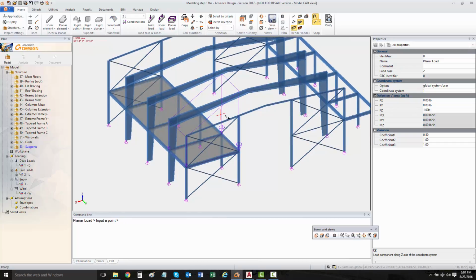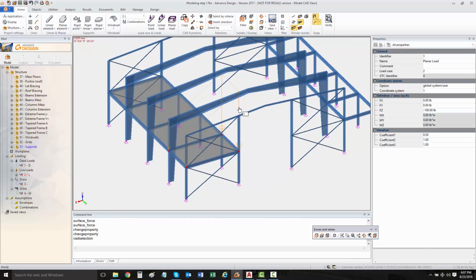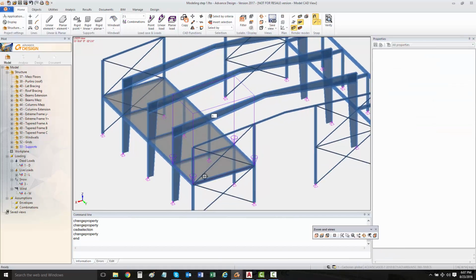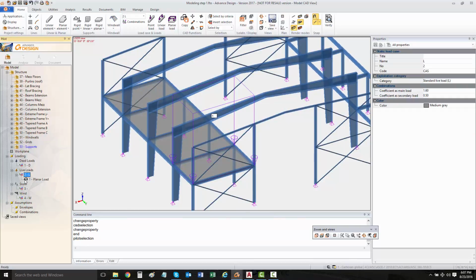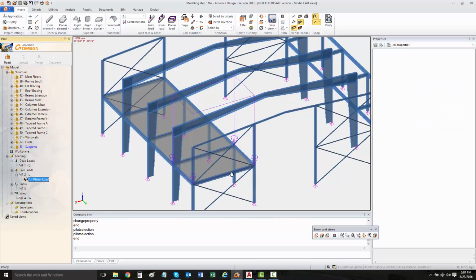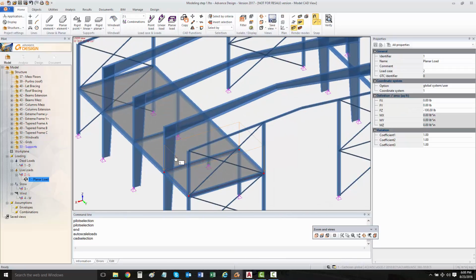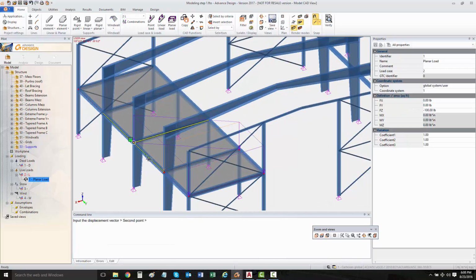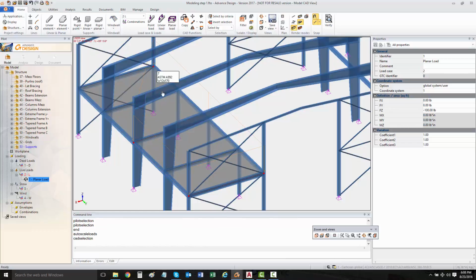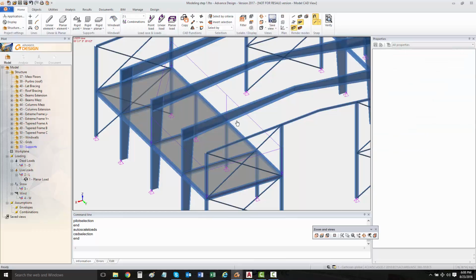And so we could see that we could also create trapezoidal. So I have it here depending on the coefficients. So now I have my load here, which is in my organizational tree here. I could select it. I could scale these if they're a bit too big. And obviously, we always have these grip points that we could go and create. And so it doesn't need to be always a square shape.